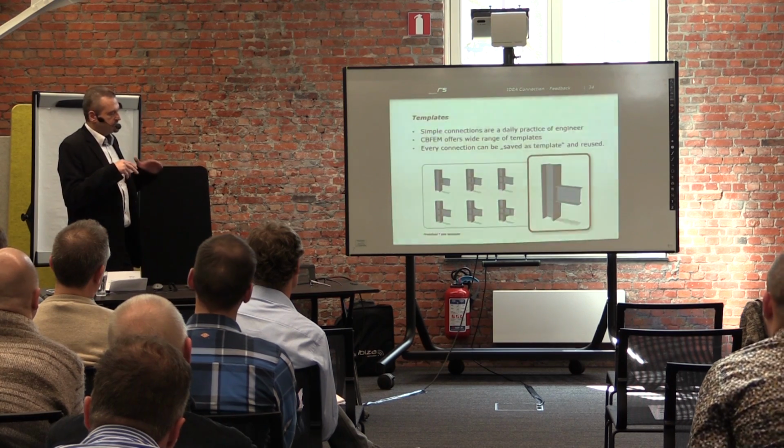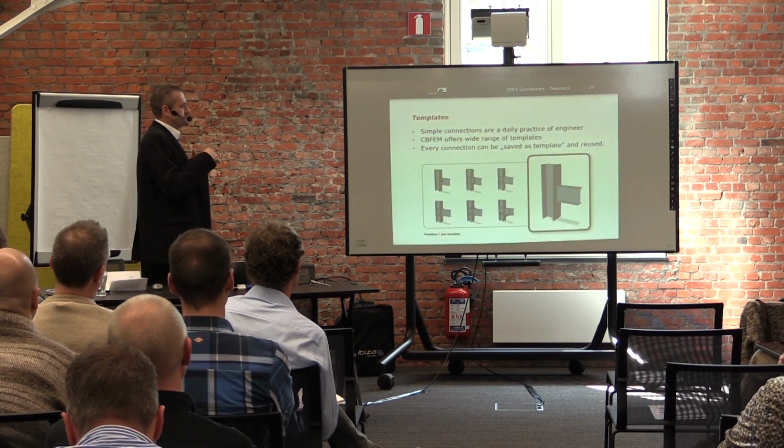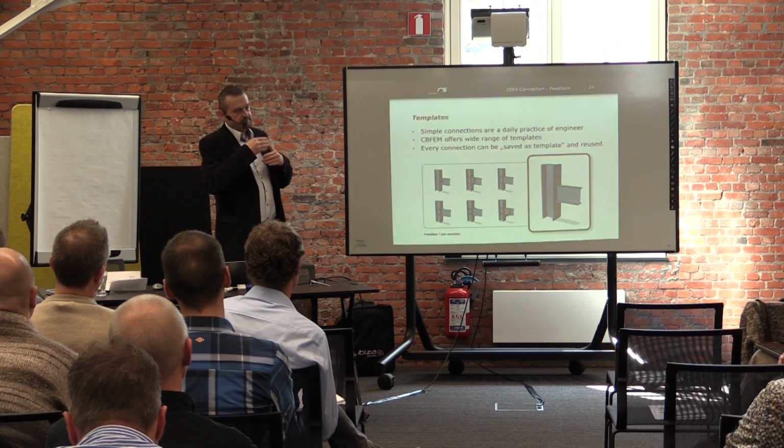I spoke about these manufacturing operations, and the template is in fact the sequence of these operations. Like at first you must have a cut, then you weld the end plate, then you define the grid of bolts, and this sequence is saved.